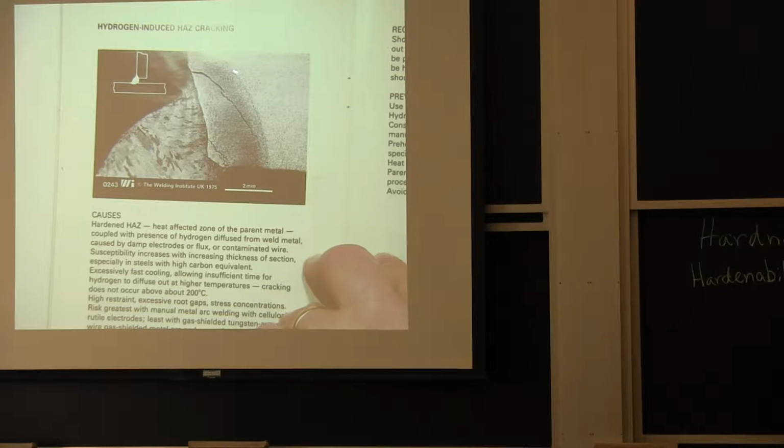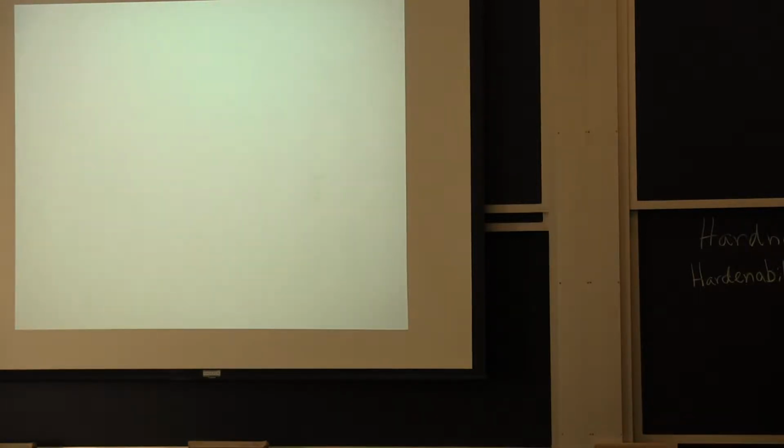And there is a residual stress pattern here. You don't get cracks unless you have stresses, but just from the fact that the fusion weld is made by having localized heating, you're going to get localized stresses. The localized heating produces, on cooling, due to the thermal expansion differences, the residual stresses, and those residual stresses can result in cracking.